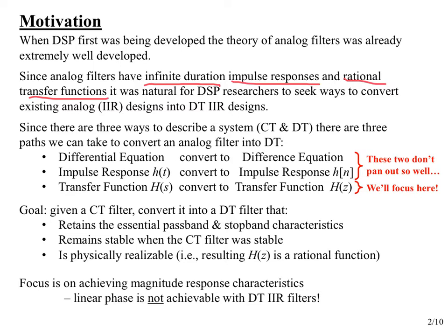That's the crux of this issue, the difference between the S-plane and the Z-plane. The S-plane, remember, has the j omega axis dividing left half plane and right half plane, and poles have to be in the left half plane for stability. The frequency response lies along the j omega axis, whereas on the Z-plane, our frequency "axis" becomes the unit circle, and that's what accounts for the periodicity of DTFTs. That unit circle is the dividing line on the Z-plane, in the same way that the j omega axis is the dividing line on the S-plane. So for stability, we need poles inside the unit circle, and so the basic topography of the Z-plane for digital filters is very, very different.